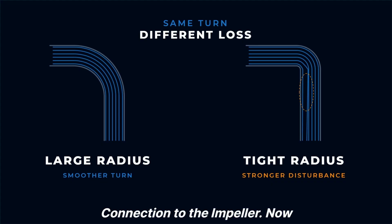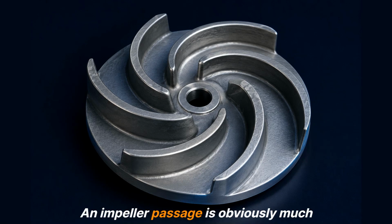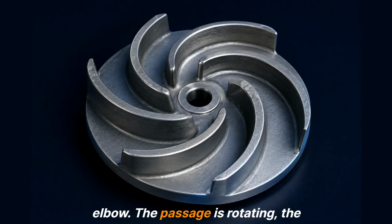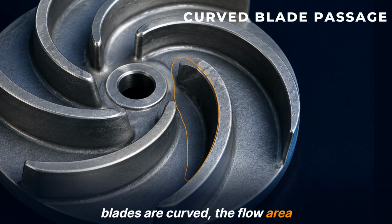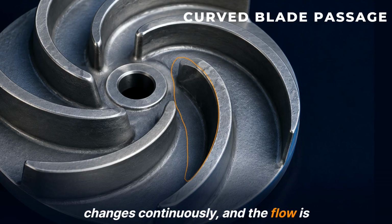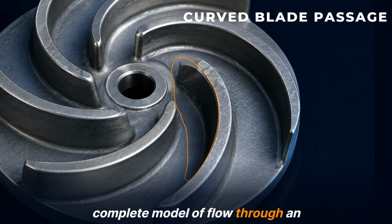Connection to the impeller. Now return to the centrifugal pump impeller. An impeller passage is obviously much more complex than a stationary pipe elbow. The passage is rotating. The blades are curved. The flow area changes continuously, and the flow is three-dimensional. So we should never treat the simple pipe bend equation as a complete model of flow through an impeller.